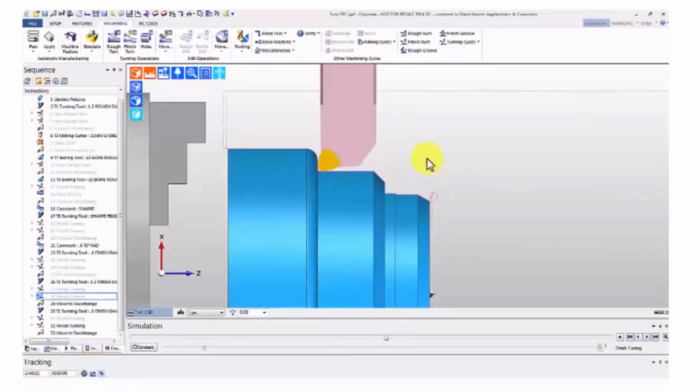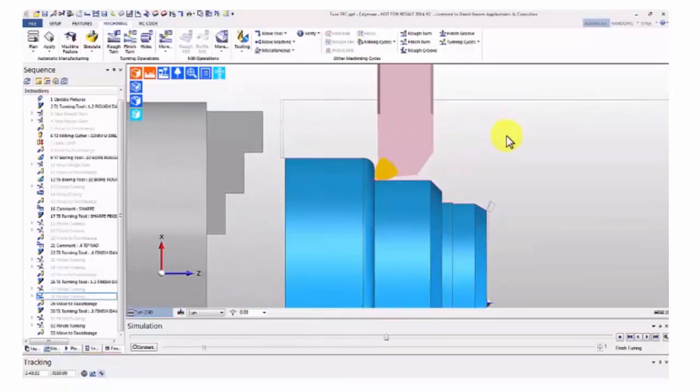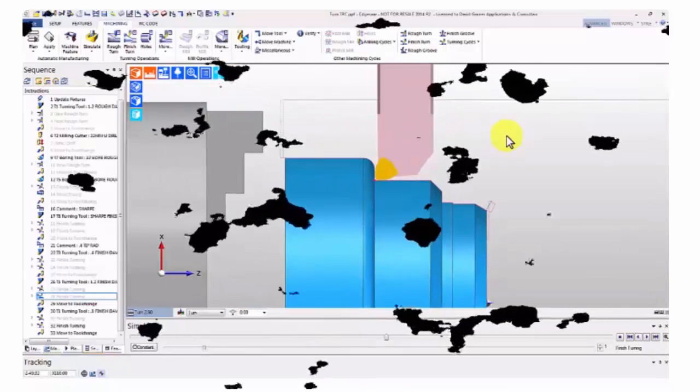This is one of the problems: if you build up a great big CNC program and it's all ready to run and you run it and you start getting errors, you're dealing with this mammoth task. But if you can break it down into small manageable chunks, then it's quite easy to work out where your problems are coming from. So that is what we call the look ahead, and that is why in tool nose radius compensation, G41, G42, it's got to look ahead.